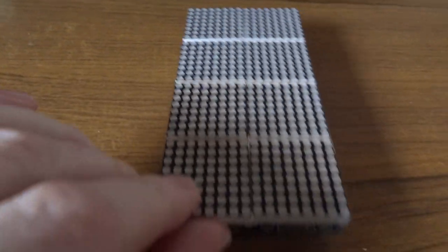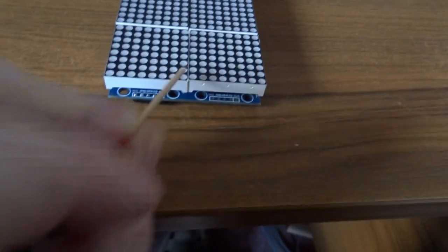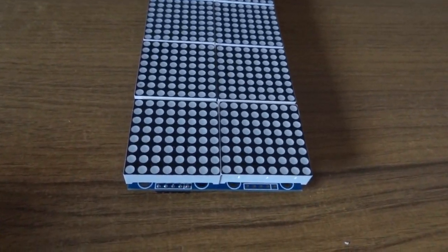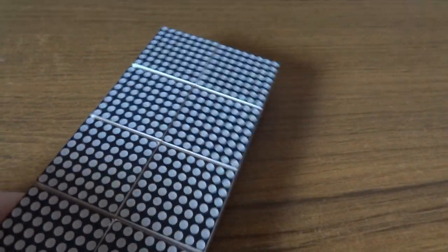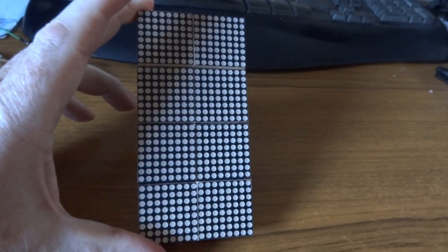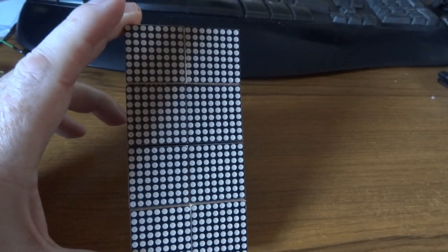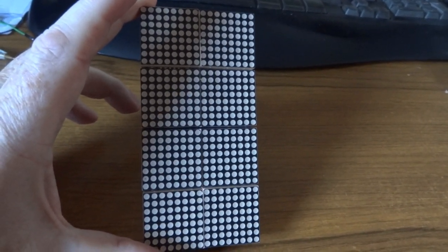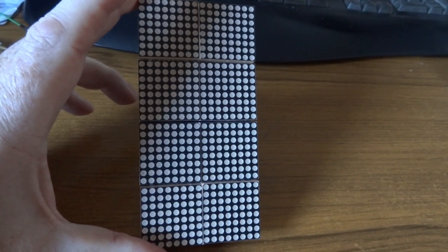Whereas the other way, whether you've got the 4x1s or 4x2s, the chips butt up against each other, and then the spacing between the individual dots can remain consistent across any number of blocks. So it's actually better, if you're going to use an array like this, and you want it to be at least 32 pixels high altogether, to put the blocks in like that, with the boards arranged vertically. So that's what I've done.